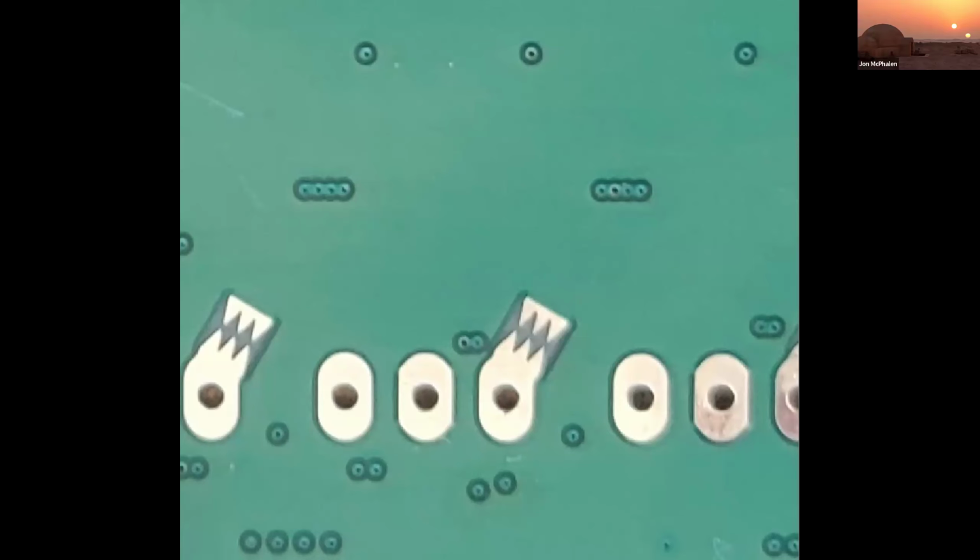Chip, without solder mask underneath the teeth, do you have to worry about bridges when you're doing the selective soldering? I don't think so. We're going to find out, but I don't think so. Because the board doesn't have much more affinity for solder than the solder mask does, the FR4 underneath.